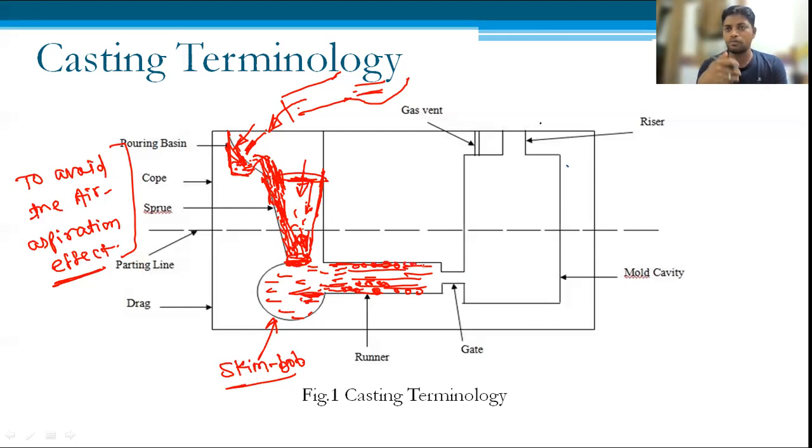Okay, so there is a possibility that this kind of formation can be possible, not formation, but the bifurcation can be possible. Sometimes we can use vibration so that the small density particles move toward this side, and the high density particles move toward this side, and then, as this liquid metal continuously comes, because of that pressure it should move towards the gate side.